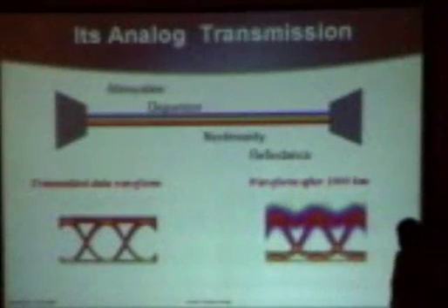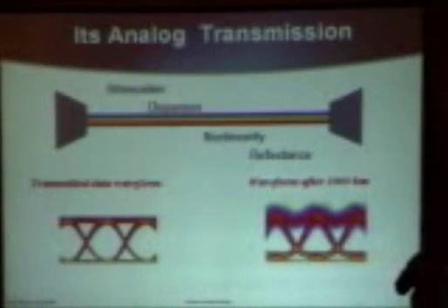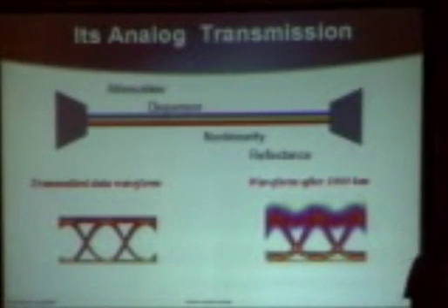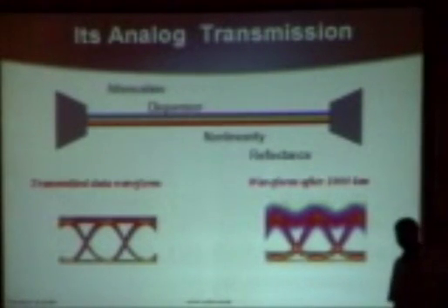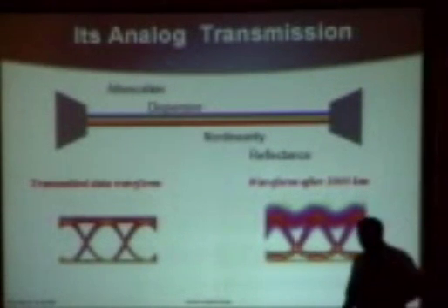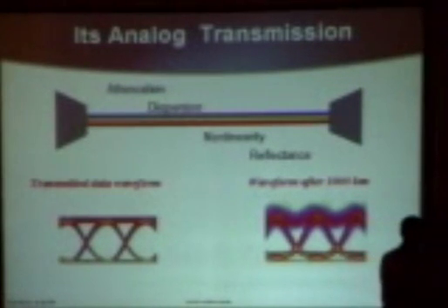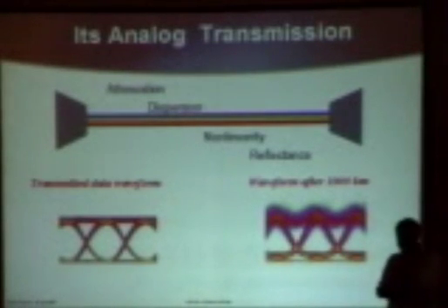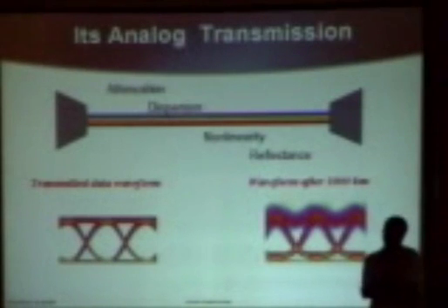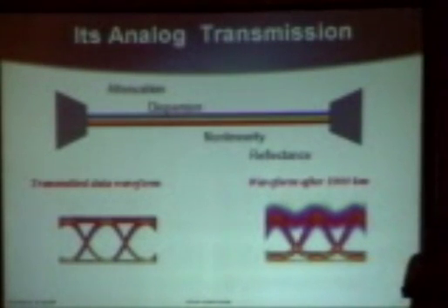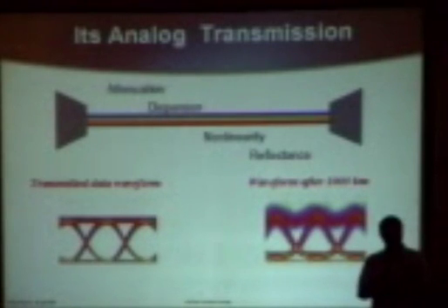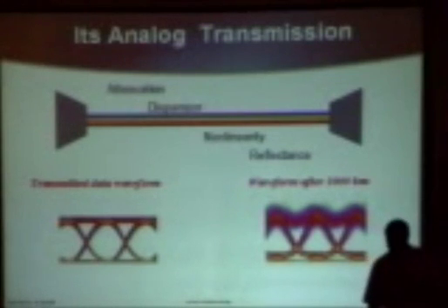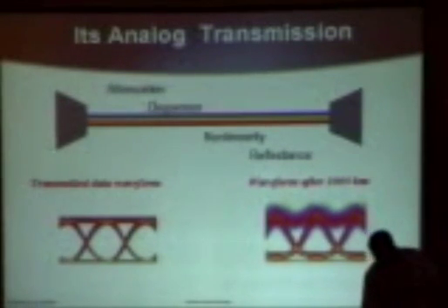Well, although that was a digital problem, the message to you when you enter the fiber world in transmission is that it's an analog problem. It's always been an analog problem. It continues to be an analog problem. And the major consequence of it being an analog problem is that it's very difficult to have mid-span meet, as we talked about with Sonnet last time. Today's setup is that every single WDM system does it differently at the physical layer, down at the analog problem. And you can't plug vendor A into vendor B. And I personally feel it'll be quite some time before you ever have a chance to do that.